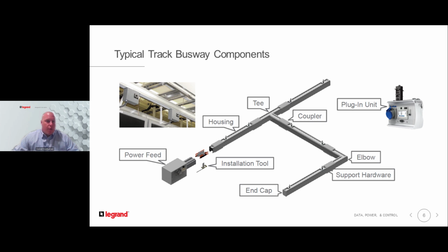And continuing to look at the overhead busway solutions, overhead busways do not require any cable or ladder tray or raised floor to distribute power. Since the busway has readily accessible receptacle and cord installations, the installation of those devices and moves are simple. Also, because the tap boxes are factory assembled, you eliminate the time and cost associated with on-site wiring to build and terminate those circuits. We can also offer power monitoring in our end feeds to monitor the entire busway run, or the individual plug-in units to monitor at the branch circuit level.